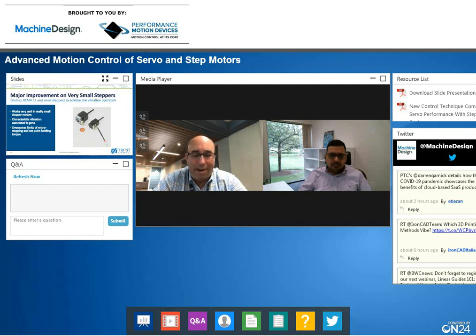And for this particular application that we were working on, we started with the NEMA 8 that's on the right-hand side of the penny. And, for torque reasons, we didn't have enough torque in that motor, on the second application. So the first application is using these motors. The second version of the machine, they needed more torque. And we had to fight to get to use the motor that's above the penny, the NEMA 11, because there was just such tight space constraints.